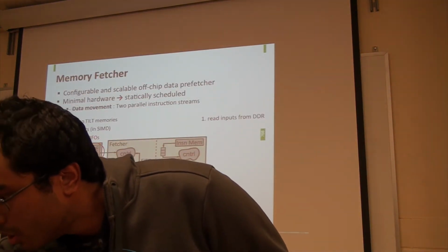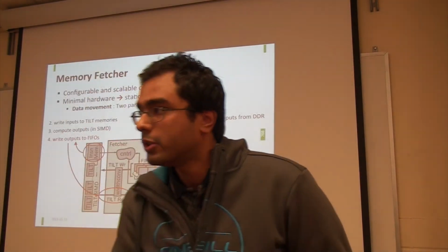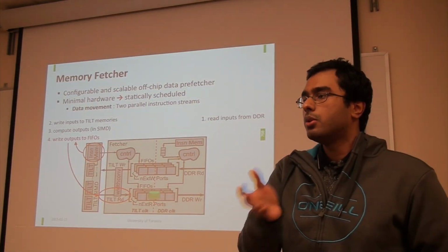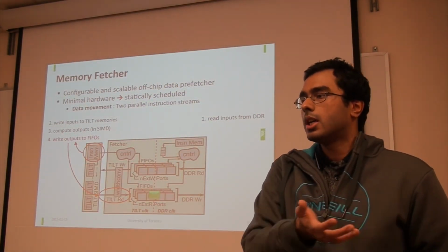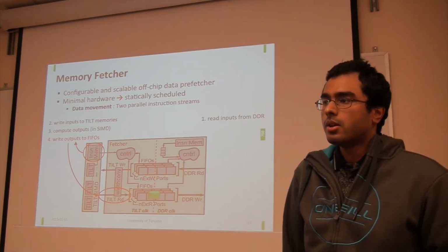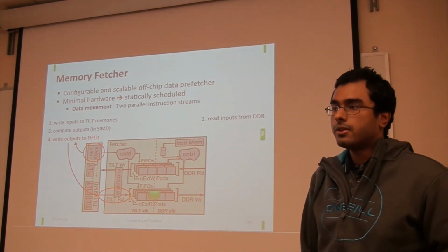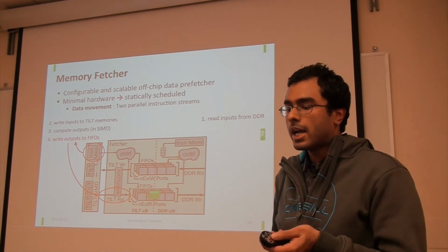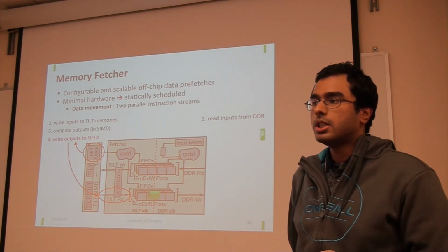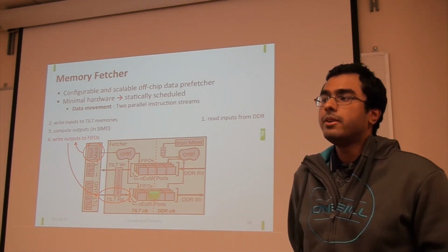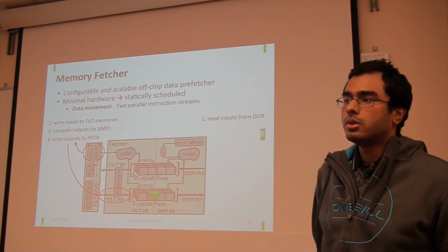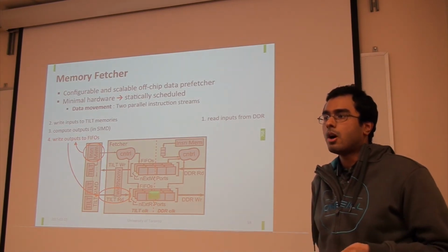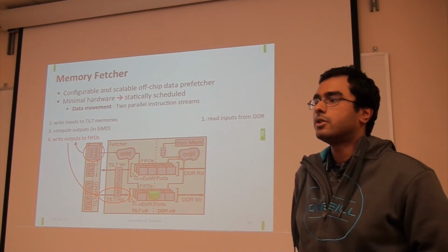So instead of connecting these FIFO channels to DDR memory, you connect them to PCIe or some other external source. There wouldn't be any significant difference in the actual architecture, because you essentially need to buffer or prefetch the data into the FIFOs anyway to improve the latencies to the source.